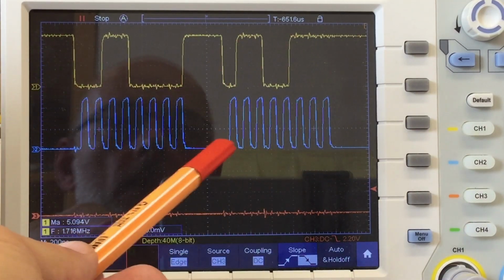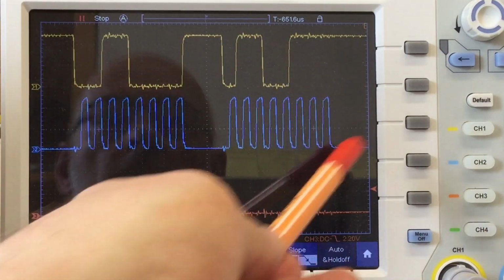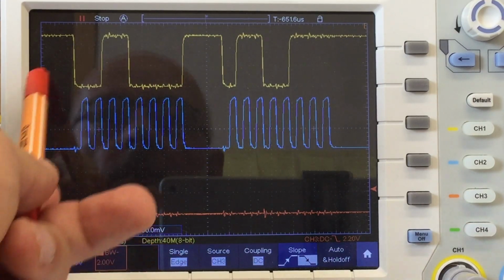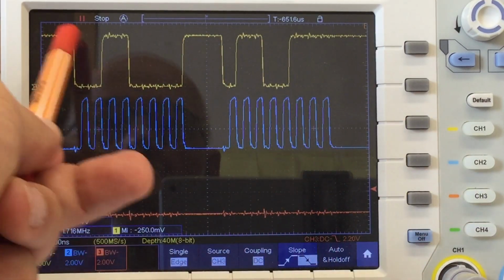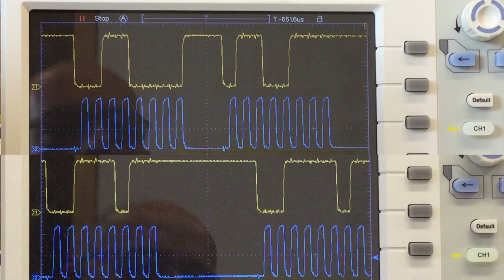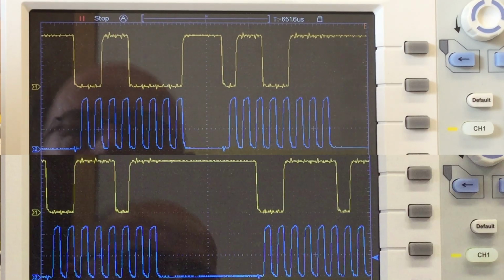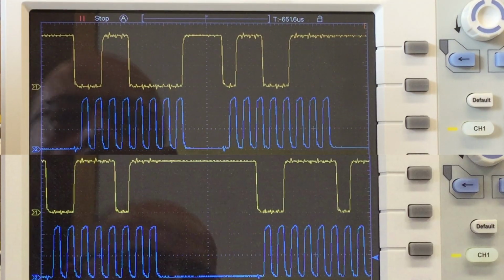You remember my code? I have called it only once to transfer 16 bits. If you compare that to what the MCP4922 library generated, you see that the gap between the 2 8-bit data bursts is longer. And that's the library not making optimal use of the Arduino SPI library.